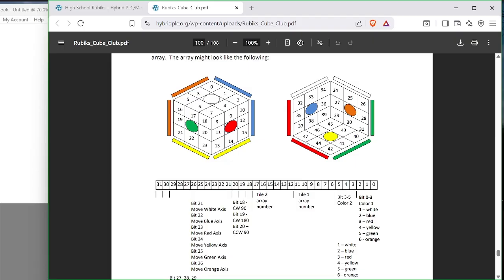Do you see how you can start creating the logic for this by just going down an array? And how many move statements do you have? One. One move statement. So instead of having all these move statements and all this logic spread out all over the place, now you basically crunched it down to an array in a very small program.